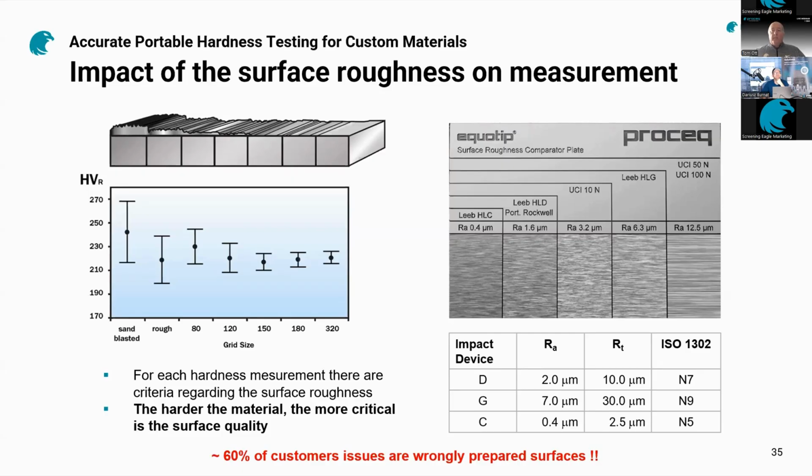So it's very, very important to use the proper reporting notations, especially whenever you're looking at converting from Brinell values, because frequently people are reporting Brinell values, even though the standard says you should be reporting HBW for hardness Brinell with a tungsten carbide indenter.